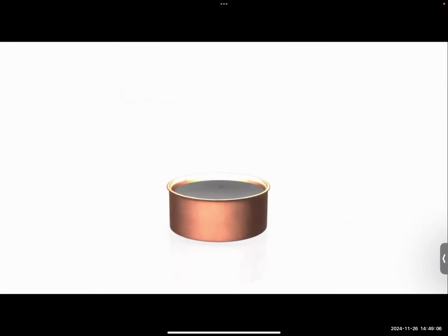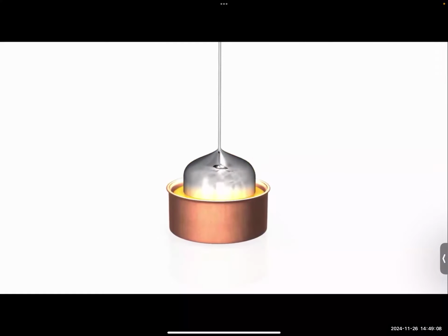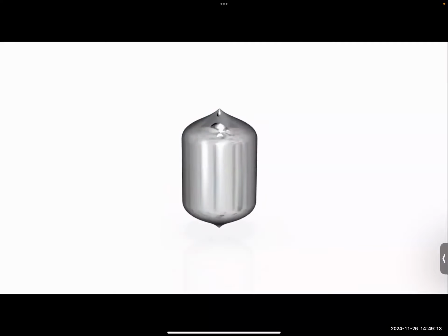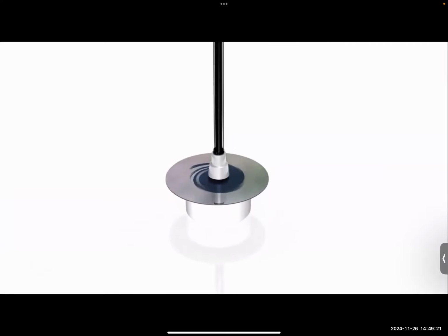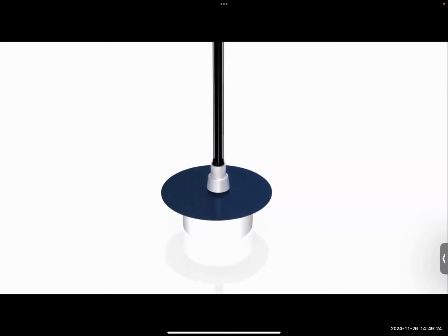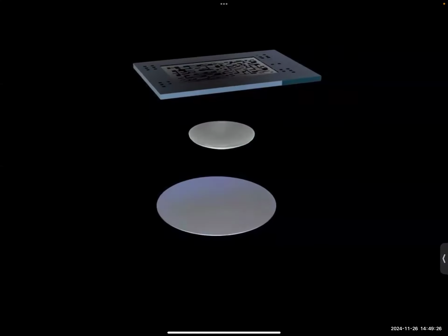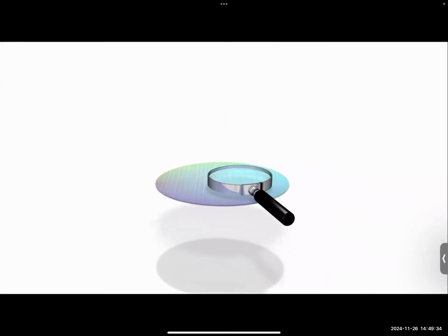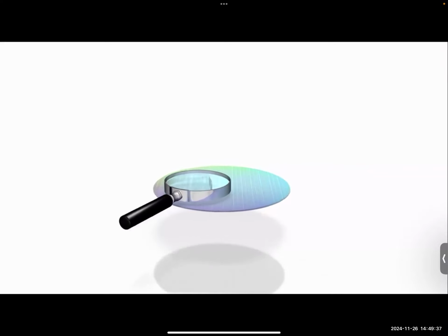I want to show you a video as to how we go from sand to silicon. So this is literally sand, okay? You take the sand, you melt it down in a crucible, literally melt it down, okay? And you cut them into small circles. These are called silicon wafers. They are basically made of pure silicon. And then you use some sort of doping, a chemical process, to make them into N-type or P-type semiconductor. And then you use light to create patterns. So when I say making MOSFETs or BJTs, they're all made with light, okay, to maintain the highest precision.